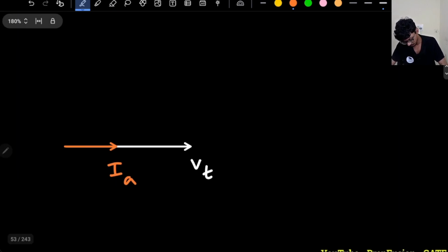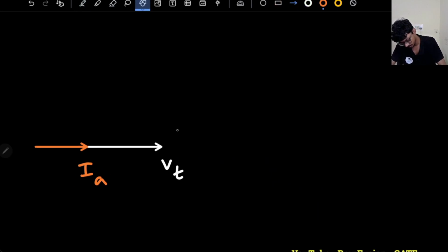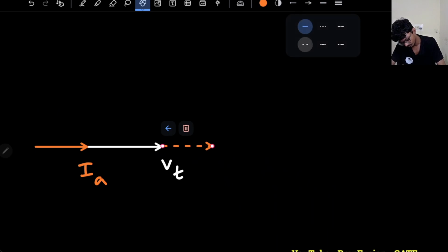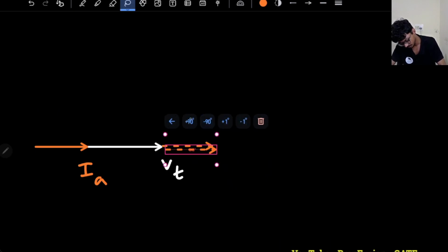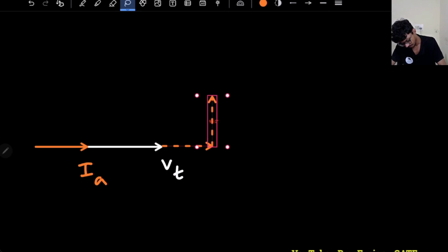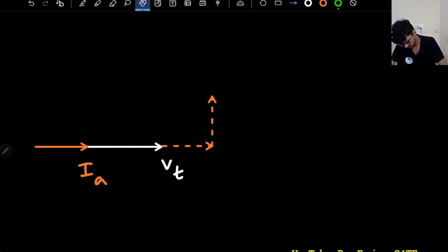This will be my Ia Ra drop. And a 90-degree shift to this will be my Ia jXs drop. And my E will simply be this.